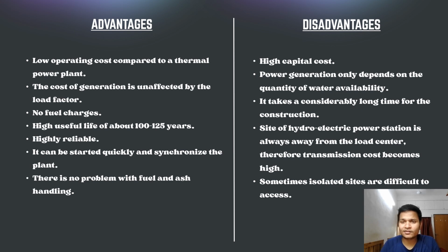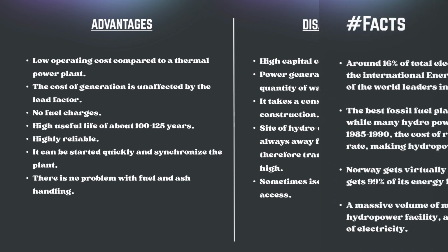Its disadvantages: high capital cost. Power generation only depends on the quantity of water availability. It takes a considerably long time for construction. The site of a hydroelectric power station is always away from the load center. Therefore, transmission cost becomes high. Sometimes isolated sites are difficult to access.